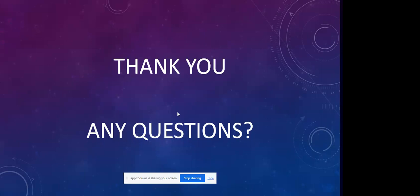So in so doing, elements that naturally are poisonous to the environment, we are able to take them out in the chemistry because it's artificially created. So synthetics are better. In terms of their reaction with seals and materials, they are better. They give you a longer drain interval. In terms of oxidation, they are slower to oxidize. So synthetics are better. It's just that they are expensive because of what goes into their blending.